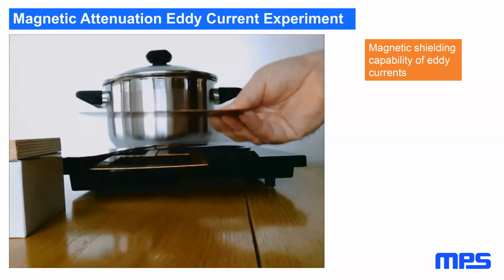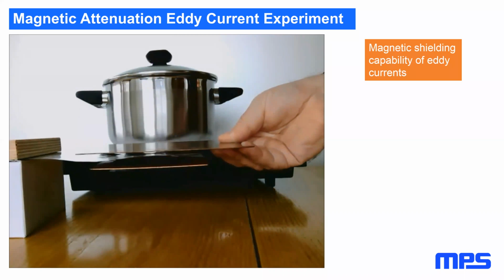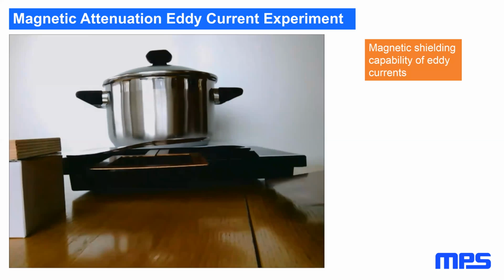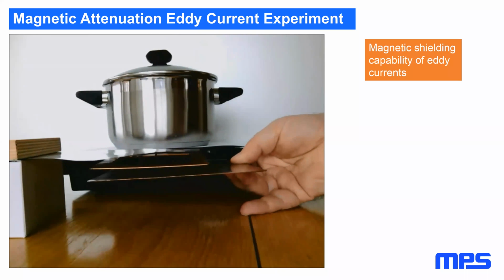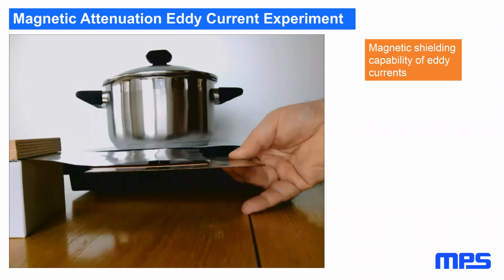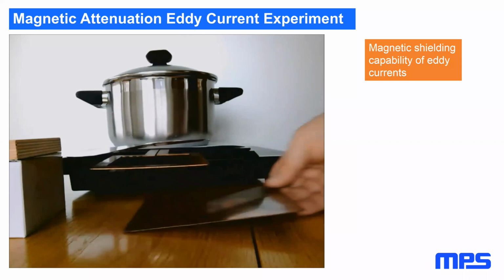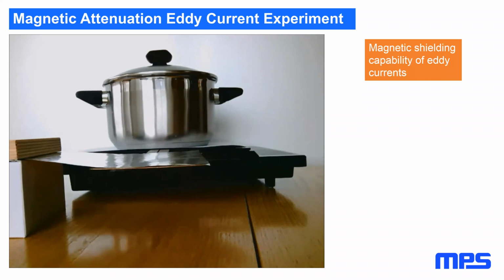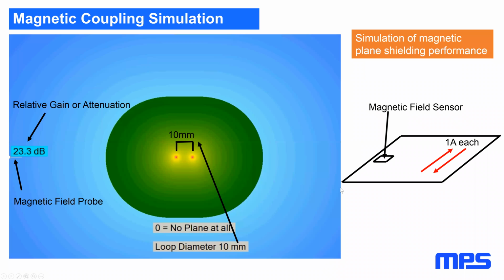And that's actually the operational mode of any plane you put under your hot loop, which creates a lot of magnetic noise. That typically shows you that on a PCB with multi-layers, you can reach a lot of attenuation on the magnetic side if you put a solid plane under it.